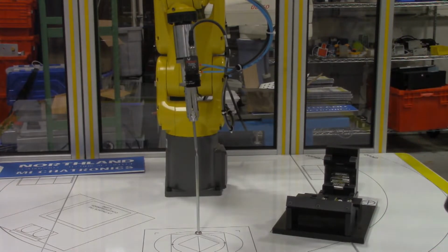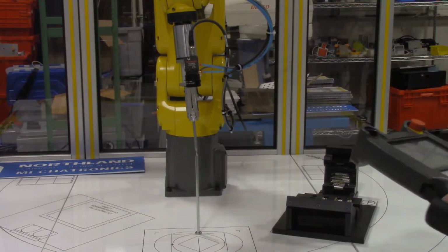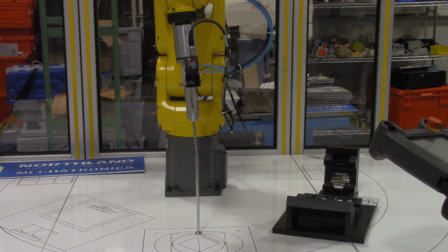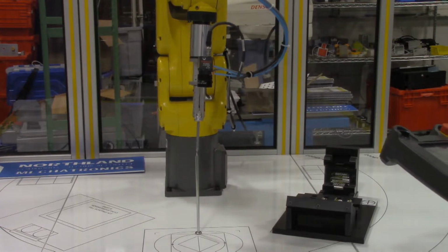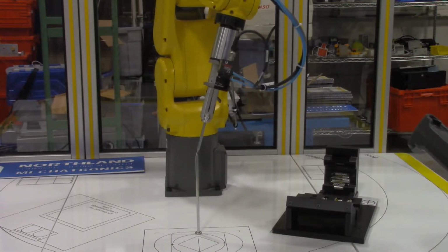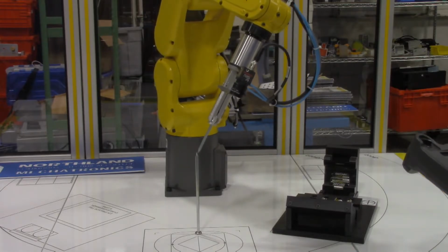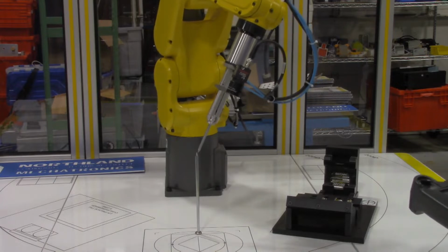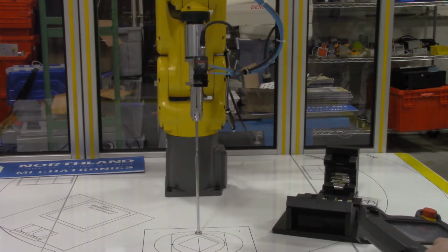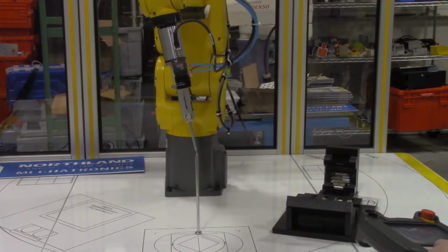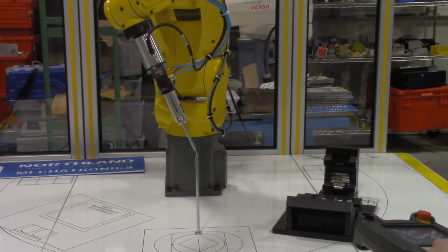And now with the new tool frame set up with the correct length, we can go ahead and rotate about the minor axes and see if it's doing its job. If we did it correctly, those two tips should pretty much stay together as it's rotating across here. And it looks pretty decent, actually. They're staying together for the most part.